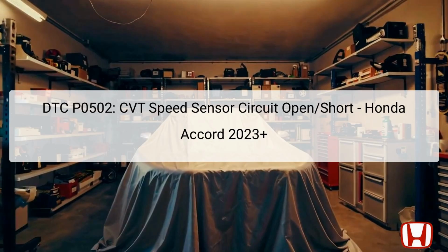The speed sensor's primary role is to provide real-time data about the vehicle's speed to the TCM, which is crucial for efficient transmission operation and overall vehicle performance. Located generally on the transmission housing, the CVT speed sensor is directly connected to the TCM via specific circuits. When this error code activates, the vehicle may experience abnormal shifting behavior, reduced performance, and could potentially enter failsafe mode as the TCM reacts to the inability to receive accurate speed data.